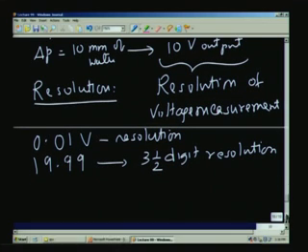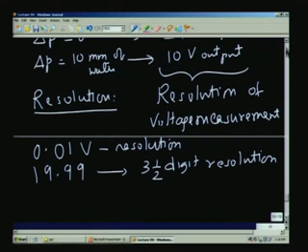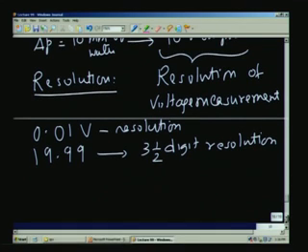So, we have, in this case you can see that 4 milliamperes correspond to 0, and 20 milliamperes will correspond to 10 millimeters of water. Okay.